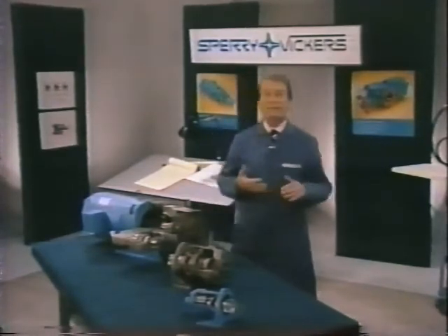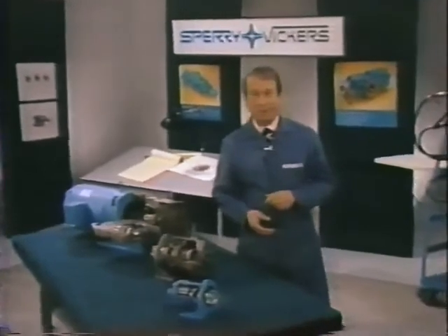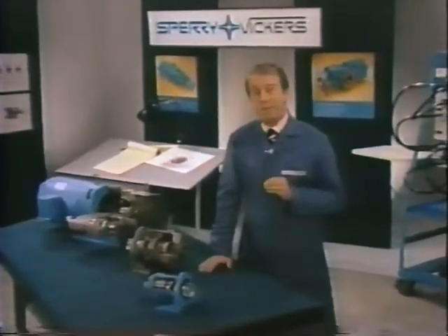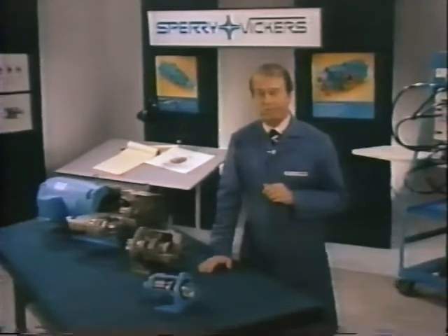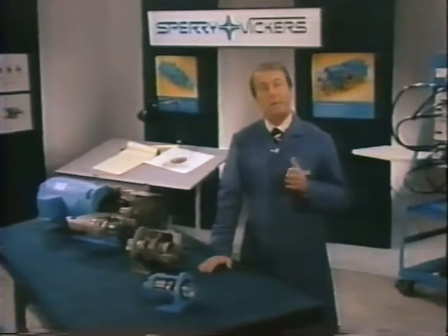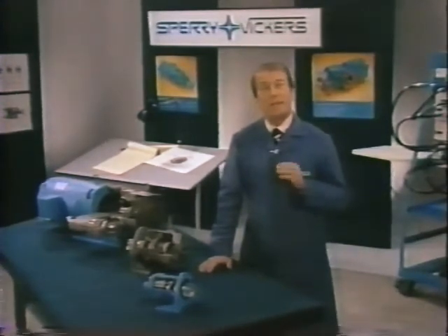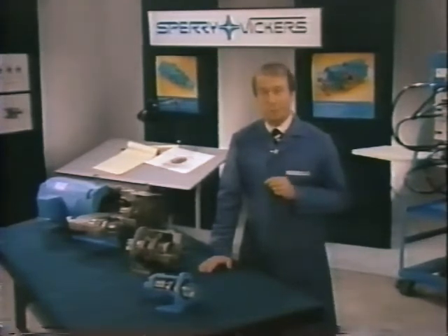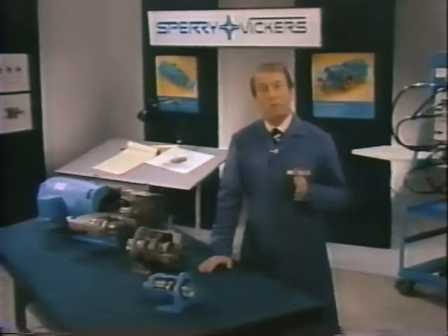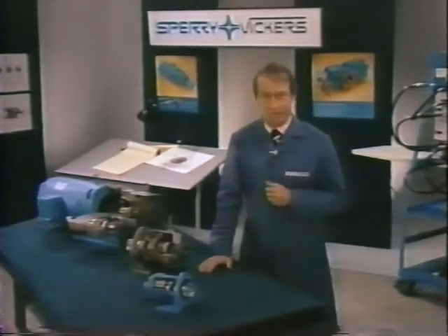Okay, that concludes our discussion of hydrostatic transmissions. In summary, these transmissions offer some important advantages. They're flexible and easy to operate. They have high horsepower in relation to package size and weight. They can be stalled without damage. The low inertia of their rotating members permits fast starting, stopping, and reversal with smoothness and precision. The output shaft speed can be varied over the full speed range in either direction, with constant input shaft rotation.